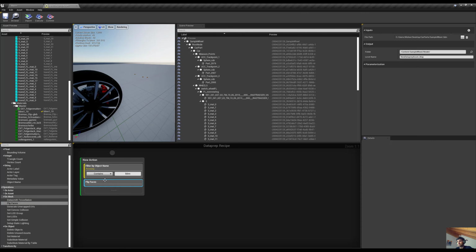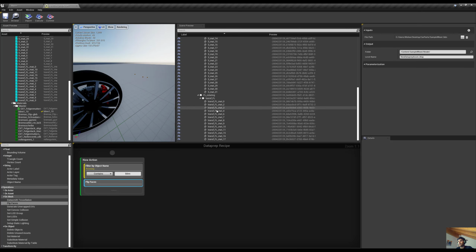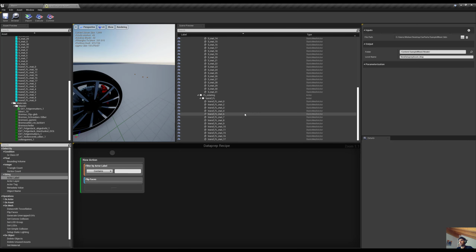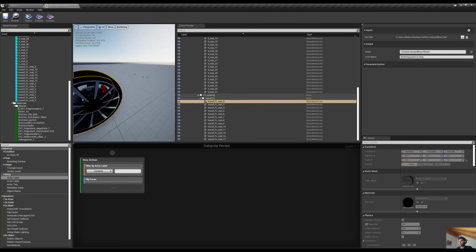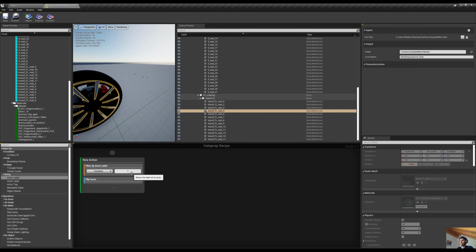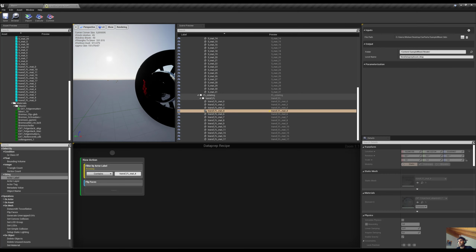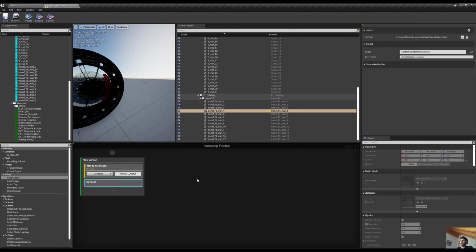Then flip faces is just if you want to flip their faces. For example, in this case, I need to grab something by actor. Okay, and then for example, this one, I want to say trans, F, FL, mat 4, put it on preview. Okay, I have it, and now I'm going to flip its faces, execute, and now you're not seeing it anymore because its face is toward this direction. So that's flip faces.